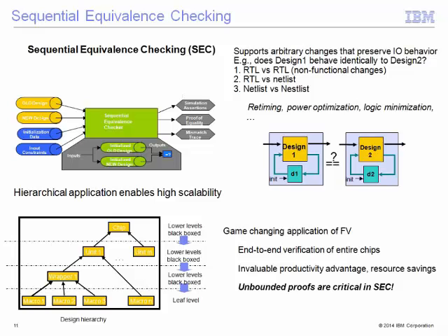Just to add from the project standpoint, for everybody working on design, typically internally at IBM, we have multiple specifications. When you are transferring your design from one setting to another, the next setting is generally a fine-tuning of the design. Sequential equivalence checking has helped us reduce the time in making sure the functionality is not broken because of those optimizations. That is the advantage that we see when we verify the same design across the two specifications. Yes, exactly. That is the same thing.